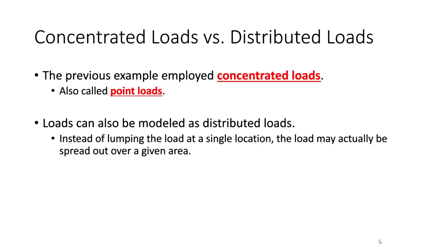A very common example of where point loads come in the real world is framing connections. For example, if you look at a floor system, you will have these floor beams framing into these larger girders, right? Here's the girder, and there are floor beams framing in every so many points. The reactions from those floor beams we treat as point loads on that girder. That's a very real example of where we would see that in reality.